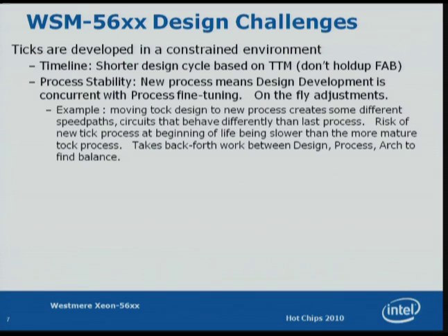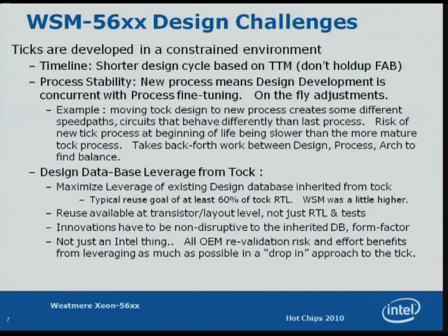The other thing to deal with in this constrained environment is process stability. Since it's a new process, there's quite a lot of back and forth that goes on, defining metal pitches, the strength of the transistor drives, and so on. There's quite a lot of back and forth between design, process, and architecture to convert a TOC program over to the new process and implementation, because the new process typically looks different than the old one did, and a number of circuits behave differently.